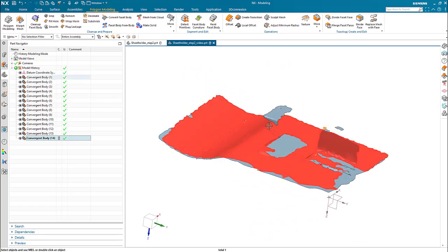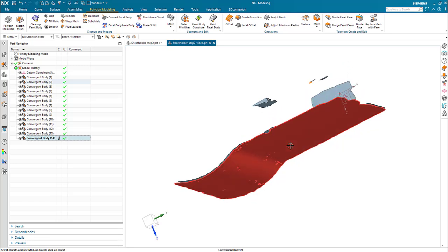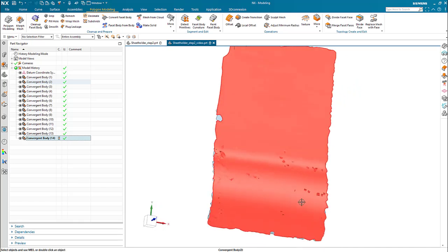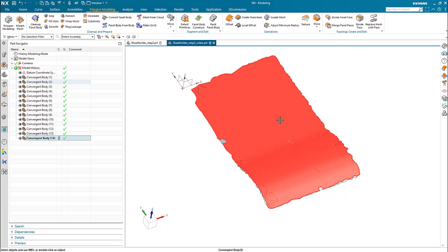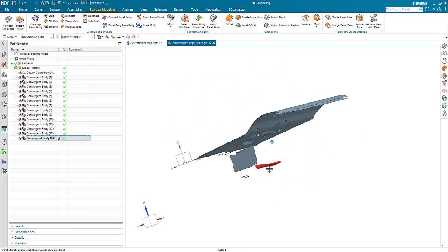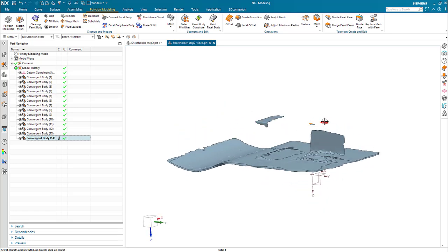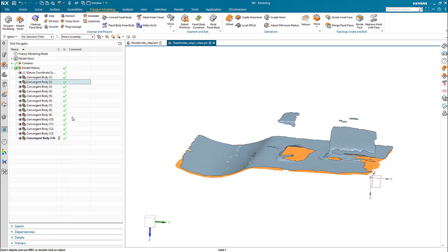We want the spacing from the bottom here to the top to be fairly accurate, so that when we put this in our CAD model and we're doing the offline programming, the placement of the pen is going to be reasonably accurate when we test our program on the real device. Okay, so we want a good curvature or a good part here, and then we want this height. Now, unfortunately, the scans don't give us a whole heck of a lot of useful information that way. So perhaps if we're doing other scans in the future, that would be something to watch out for.